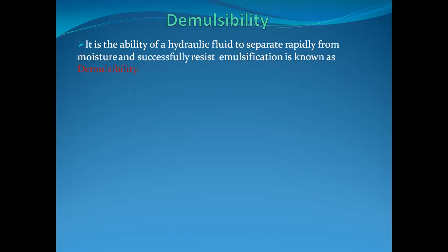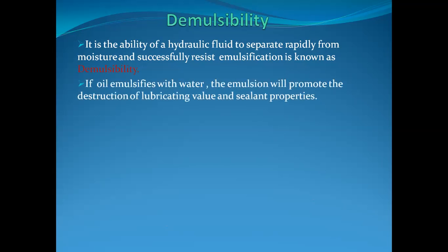That is demulsibility. The oil emulsifies with water. The emulsion will promote the destruction of lubricating value and sealant properties, meaning sealing properties. Highly refined oils are basically water resistant by nature, but they are costly.